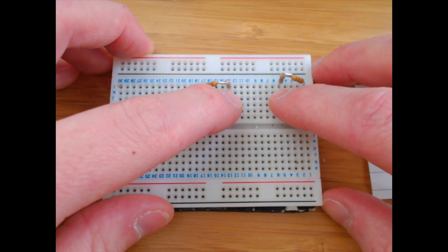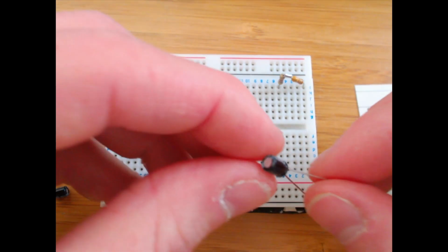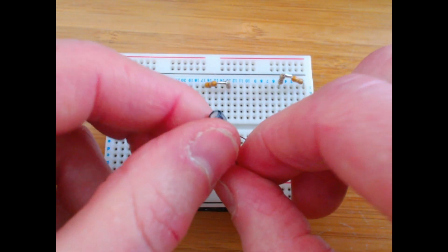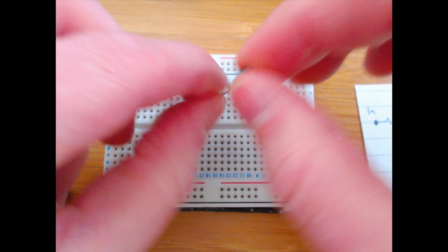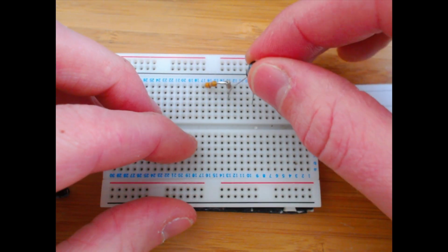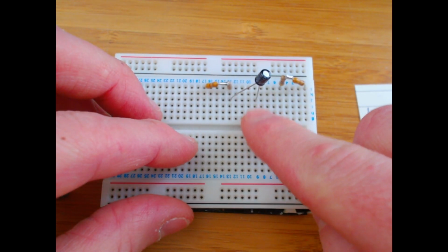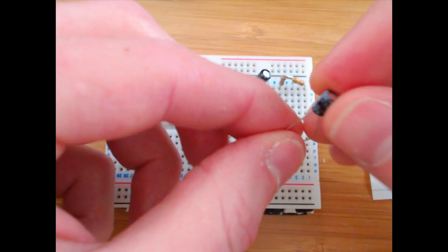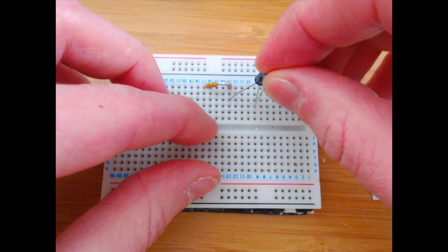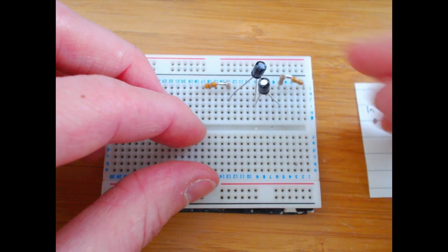We're going to pass through the resistor, the one resistor we think of it as, but it's two. Then we're going to go into the capacitor, and these capacitors are polarized, so this is the negative side. The capacitor is going to go to this middle point, that's negative, that's going to be ground. On the other side, we go through that into the same point, so they end up sitting next to each other.